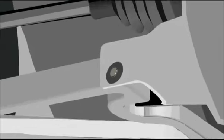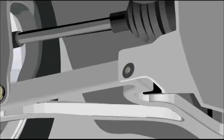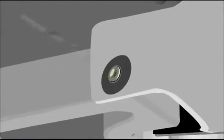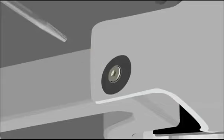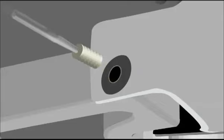If the fastener breaks off too short to grip it with a stud extractor, a technique you can use is to grind the shank flat and use a center punch to mark the center of the fastener. Then, after drilling a small pilot hole, select a left-handed drill bit of a smaller diameter than the fastener and, remembering to reverse the direction of your drill, drill out the fastener. If you're drilling out a hardened fastener, be sure to use a hardened drill bit. The drill bit, turning counterclockwise, may be enough to extract it. If not, use a threaded extractor tool to back the fastener out. To do this, thread the tool counterclockwise into the hole until it's tight. Continue turning the tool until the fastener is removed.